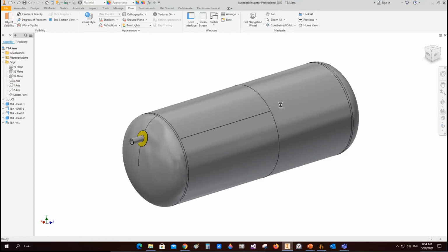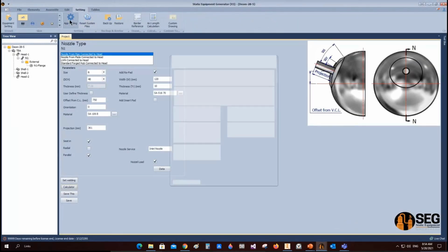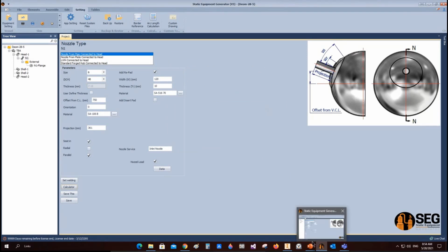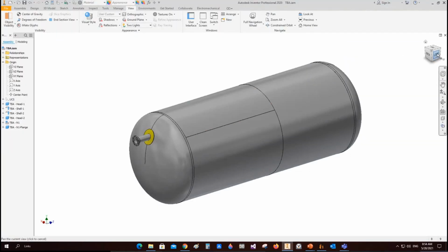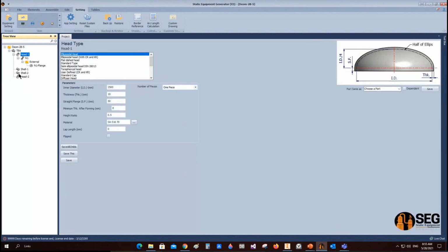Here we will need to make another nozzle with internal projection, and on this internal projection we add some attachments. So let's select this head or select the shell, for example, and from here you can see that you have many different attachments on the shell, like saddles, stacked saddle, leg lugs, skirt, anchor chair, different types of cradles, nozzle with external projection, nozzle with internal projection, nozzles according to the API with internal projection and external projection, coupling,